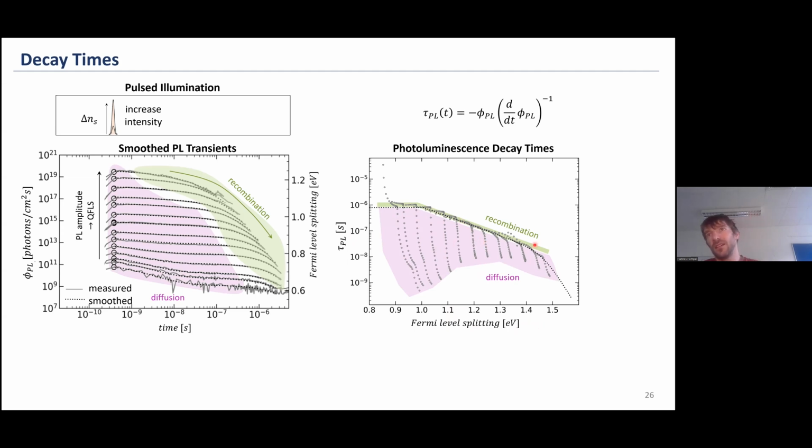And the limit into which it goes, this is actually the recombination. Yeah. So if you have a look here, if you want to find out something about recombination and want to speak about charge carrier lifetimes from this plot, you should have a look at these times up here. And then you should have a look where the quasi-Fermi level splitting is actually at the maximum power point in the VOC. And then again, this would be your relevant lifetimes.